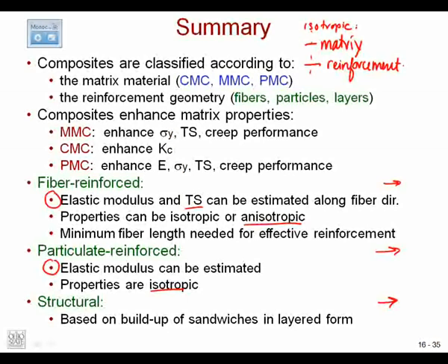So single crystals definitely aren't isotropic. What else? How could we make a polycrystalline steel be anisotropic? Still polycrystalline. Cold work it one way. If you think about a cold worked metal or a drawn polymer, it's no longer isotropic.